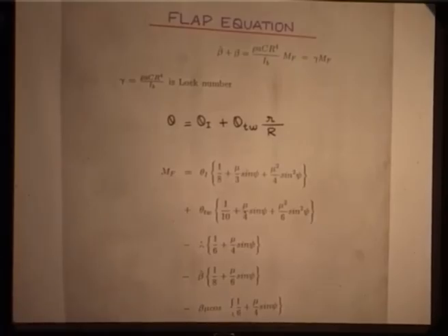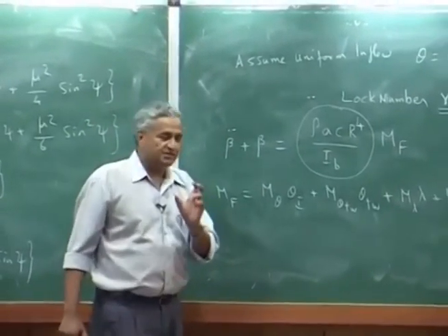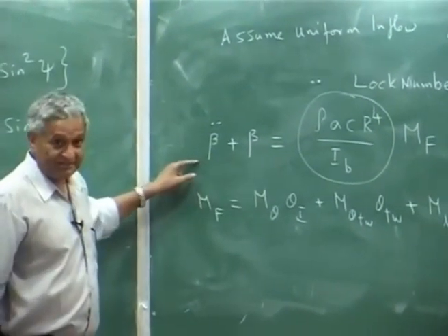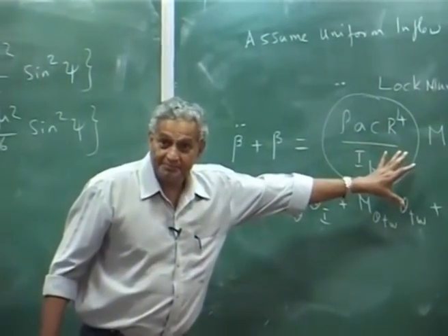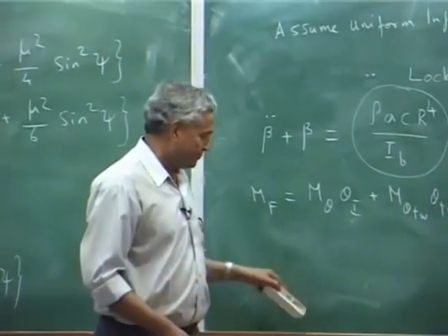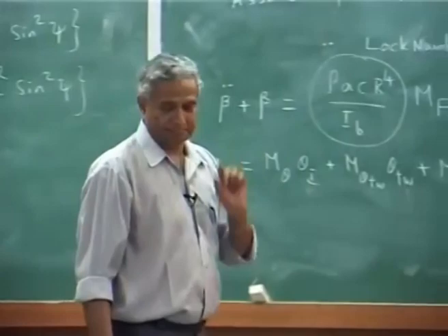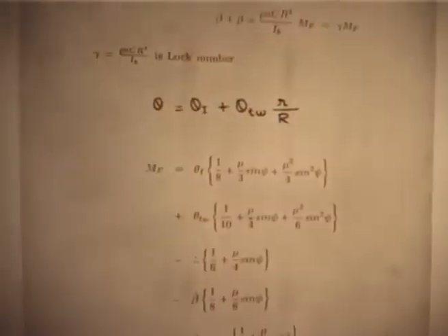That means your spring and damper. Whatever damper means, it is not actually a damper, it is a derivative term, a damping term. They are functions of psi, and psi is your independent variable. Derivative is with respect to psi. So your coefficients, please understand, left side is purely inertia. I am getting the damping term coming from aerodynamics. Please understand, in the flap motion, the damping comes from aerodynamics. So you have a spring term, which is like an aerodynamic spring.